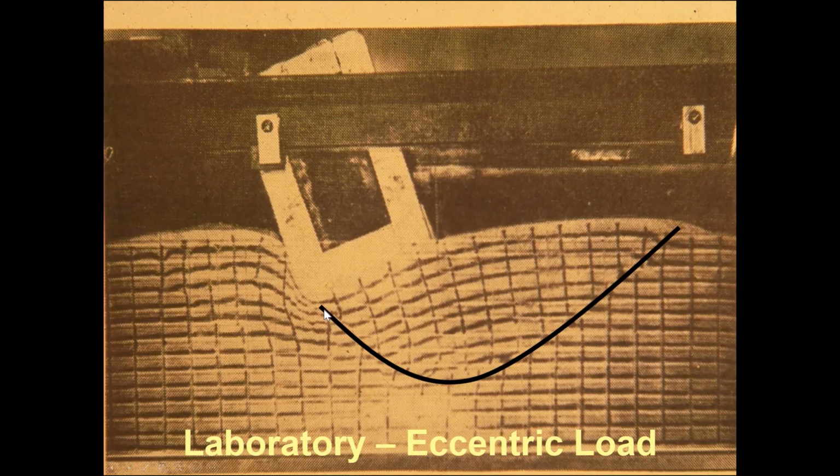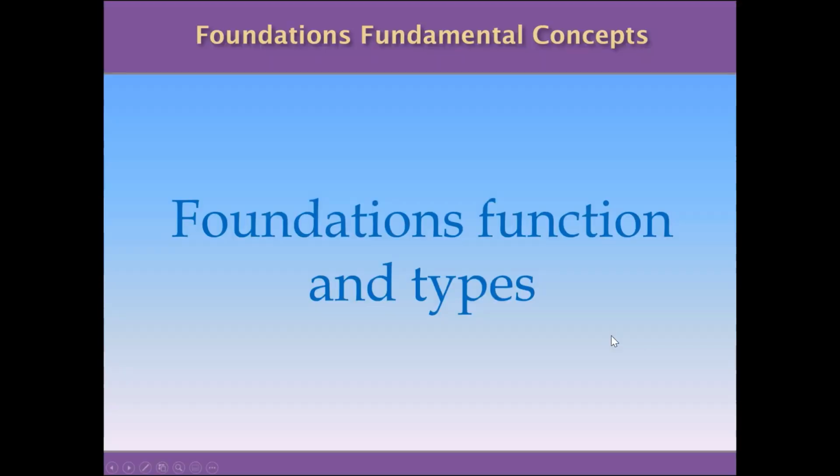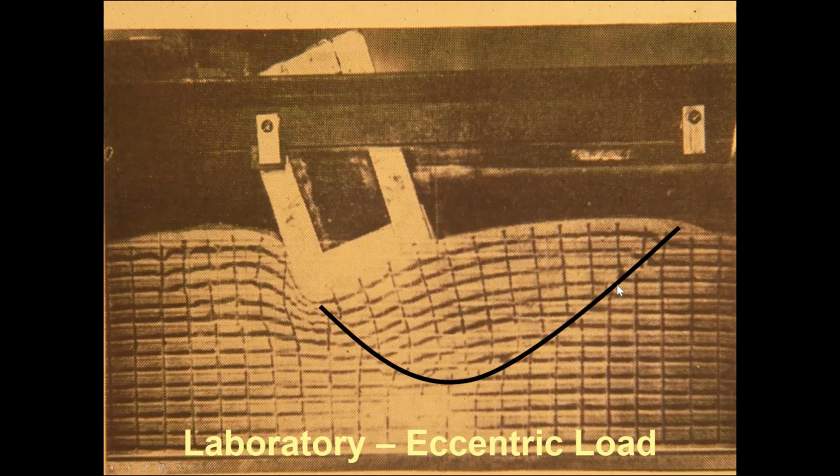Then we know that the shear strength was reached in this line, and this is the reason why the soil has failed under the foundation of this structure. So this is the reason why the shear strength is the determinant strength in soil mechanics. And this is the reason why this Mohr-Coulomb failure criteria that takes into account the shear strength is so famous and so effective, because this is what happens in reality.